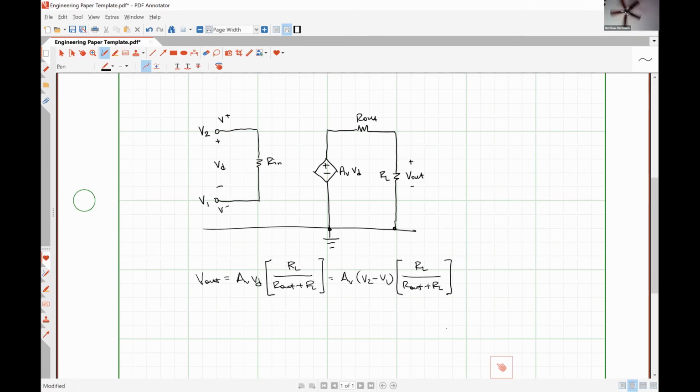Yeah, sorry. The gain is what I'm having trouble with because I don't think I've had to deal with this before. Yeah. So a decibel is how you find that: 20 log of V out over V in, where V out over V in is the voltage gain. And that's just for converting decibels? Yeah. This is the definition of how you get a decibel. So 120 decibels means you're going to have a specific voltage gain. So if we did 20 log of a million, got to find the log button on my calculator. We get 120 dB.